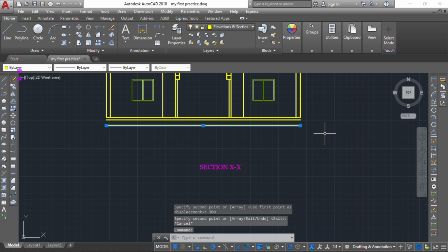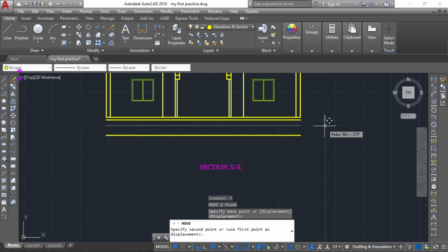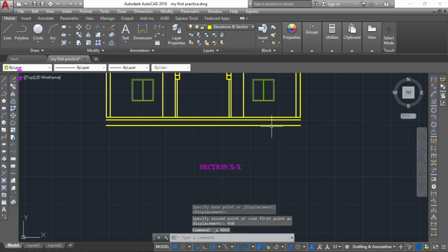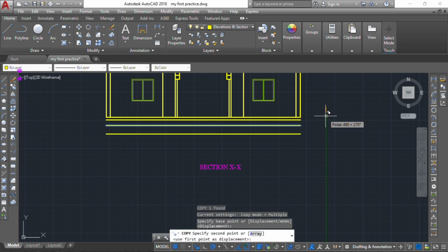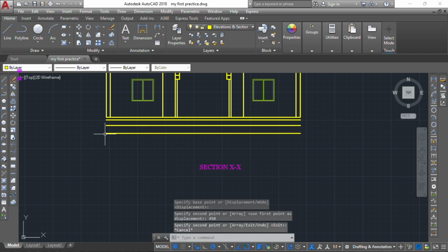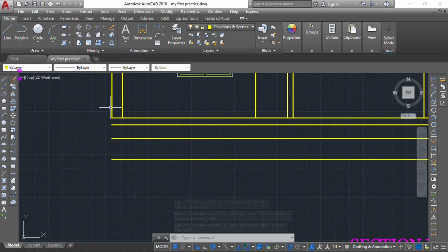And then after that, we're having the rest of our foundation footing, which is always 450 also. So everything gives you 900. Oh, sorry. We can also have 1,000. Your foundation depth can also be 1,000, it is depending. But here I'm using a foundation depth of 900, right? Okay. So now what we just need to do is to extend this up to this level, right?